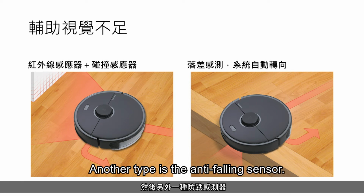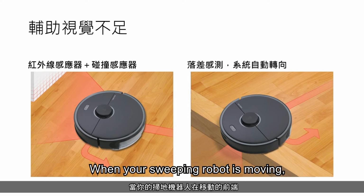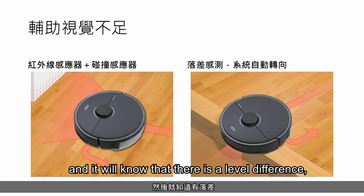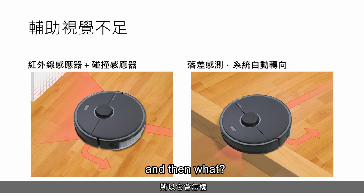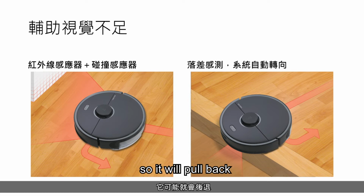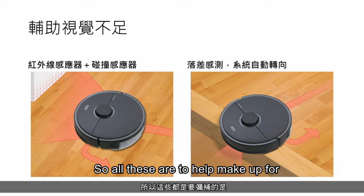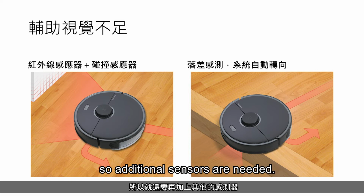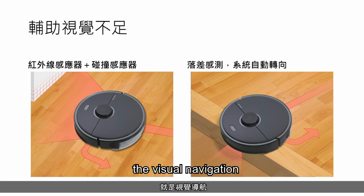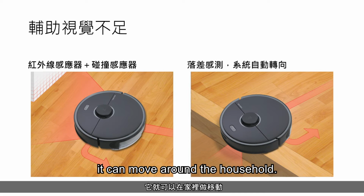Another type is the anti-fall sensor. When your sweeping robot is moving, at its front there is a sensor. When it gets to a place where there is a step, the sensor will drop down and it will know that there is a level difference. It will know that there is a step in front, so it will pull back. All these help make up for the lack of visuals, so additional sensors are needed. Through these two methods, the visual navigation and some auxiliary sensors, it can move around the household.